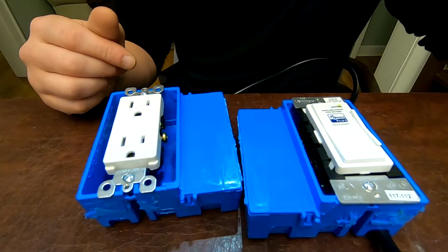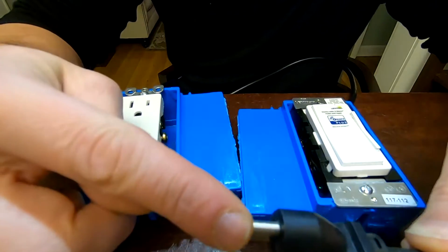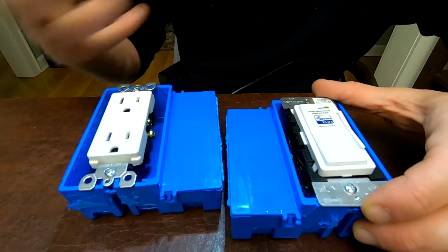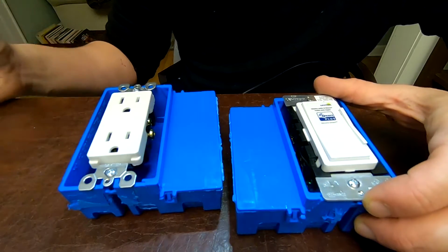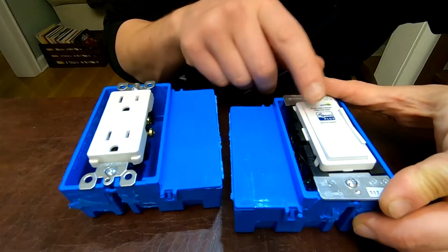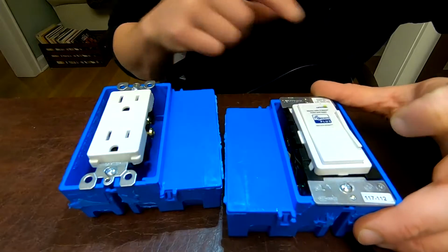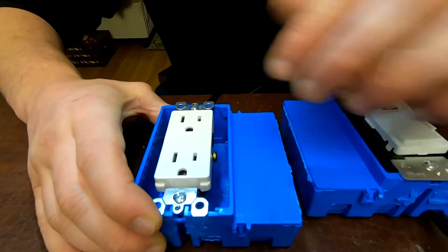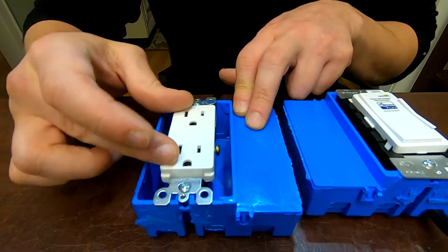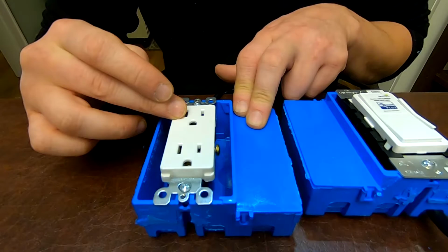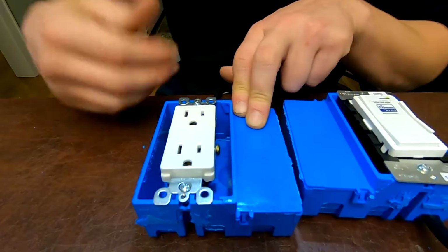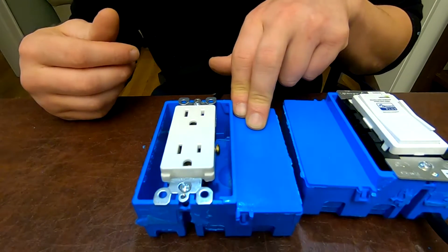Once again, power supply from the wall, 120 volts, gives power to the dimmer. Dimmer connects to the Z-Wave network, which then connects to your router or switch, which allows you to control everything through Google or through the app. It also gives you manual on, off, or dim, up, down control over this outlet, which is where the transformer plugs into and gets either on, off, or variable voltage, so it can convert it from AC to DC for your LED lights under your cabinets and dim them appropriately.